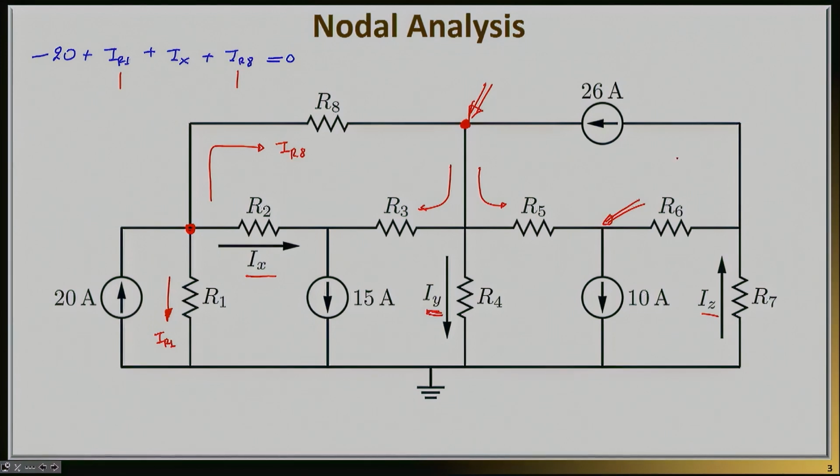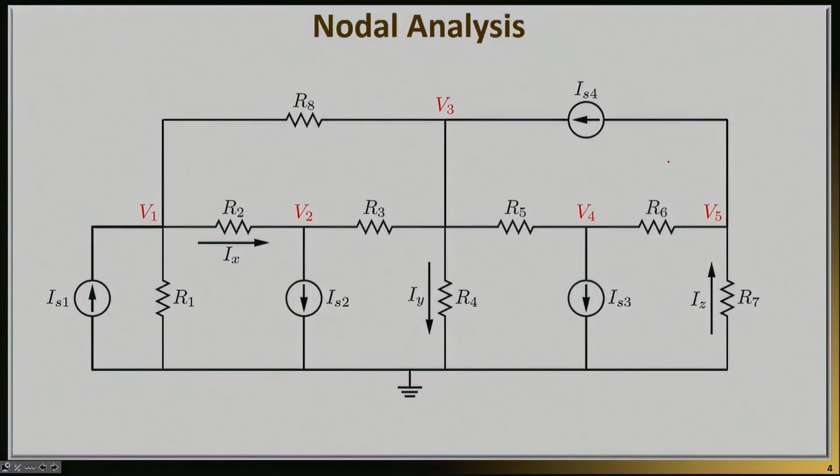Nodal analysis is exactly the solution to the problem here. In nodal analysis, we will say the following. Instead of directly finding out the currents that you need in a circuit, or voltages, or powers, or anything else that you may need, I'm going to first find all nodal voltages in a circuit. So in other words, regardless of what somebody is asking me to find, it could be power, it could be a voltage drop, it could be current, my technique will first calculate the nodal voltages in a circuit.